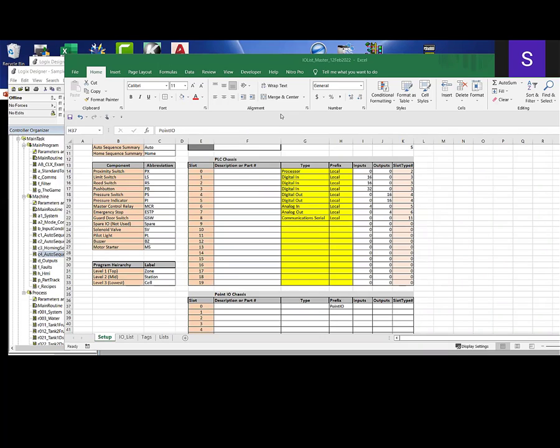Your encoder, you're going to have to put things like how many pulses per revolution that encoder is. And what the high-speed counter card does is it counts faster than the PLC can recognize physical inputs, right? A physical input, maybe I can pick it up in a couple milliseconds for one input, but with an encoder, I'm getting thousands of inputs in less than a second. So the encoder card has to accumulate those pulses and then report them back to the PLC. So every card's different, right?